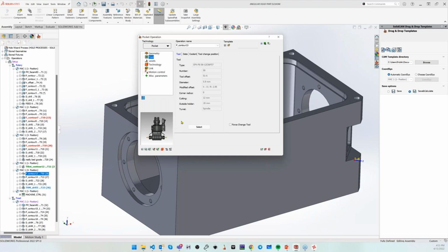In G-code, we get specific parameters which define this tool as a manual change, and you will get a special variable which you can use to define the tool and the tool change routine for the manual change. Also, you will be able to use in the tool table more tools than the capacity of the magazine defined on your tool table, and use them for your operations and parts.